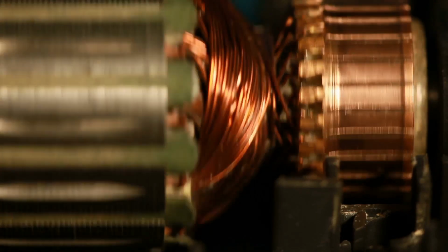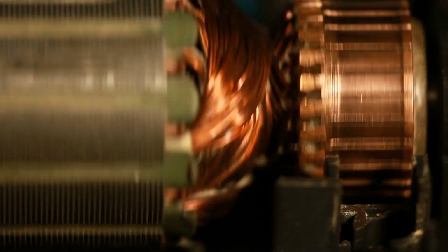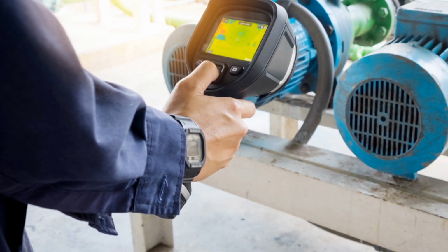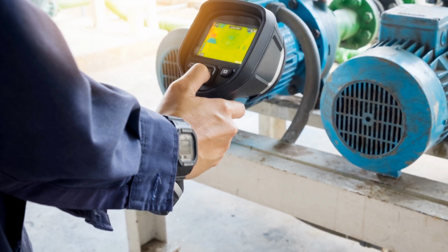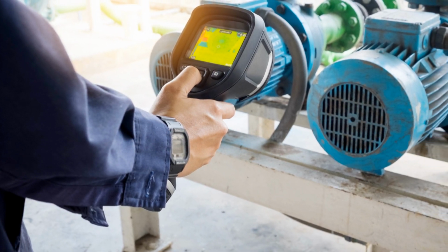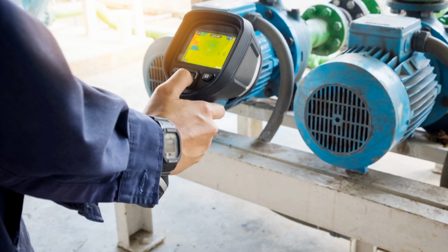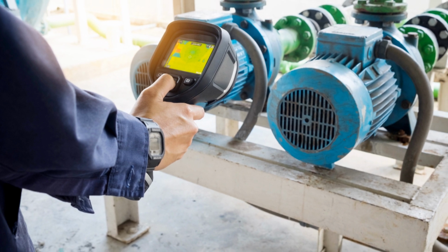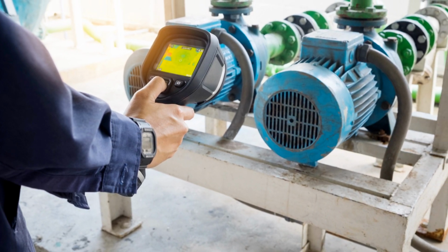When scanning equipment with a thermal imaging camera, look for abnormal signatures such as hotspots. Unusual hotspots refer to localized areas of excessive heat that deviate from normal operating temperatures. For example, electric motors are designed to function within a specific temperature range. If this range is exceeded, it can degrade internal windings, leading to premature failure. On a thermal image, this will appear as intense high heat spots concentrated in critical areas. To assess the severity, compare the detected temperature against manufacturer specifications. Identifying and addressing these anomalies early can prevent costly breakdowns and extend equipment life.